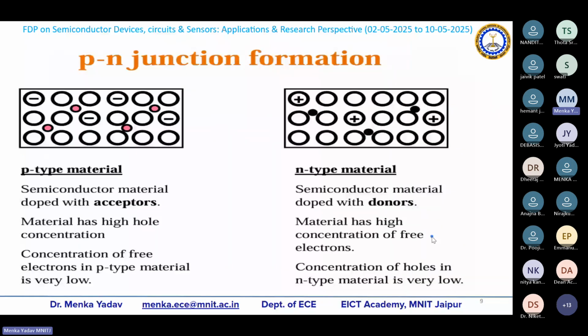For the PN junction, you have P-type material, in which these red circles are actually holes. These are holes, and these are fixed ions. Somewhere in the material structure, you will have these Na ions, the acceptor ions. And likewise in the N type, you have Nd, which are positive fixed ions, and the others are silicon. These which are not having any charge are actually silicon. And these have some electrons running. Okay. So basically, these are the majority charge carriers.